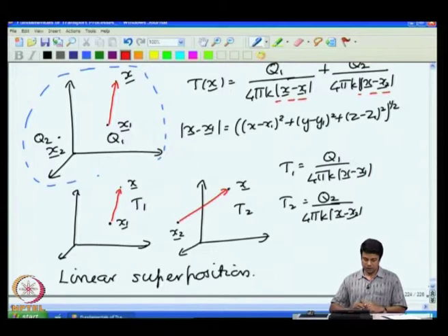I could, in this problem, for example, put in a point source which is not generating any heat, and similarly in this one, and that does not change the temperature field anyway, whereas a finite size particle will change the temperature field around it, depending upon its thermal conductivity. So, therefore, I can use linear superposition for point sources.